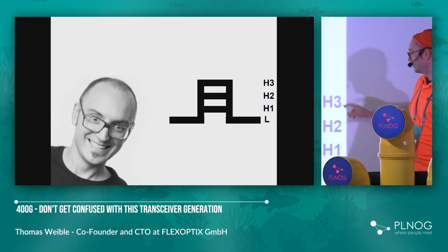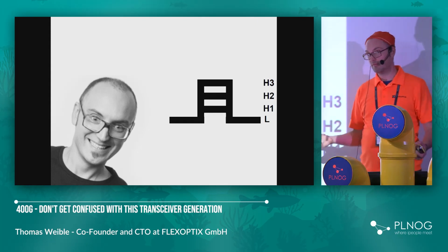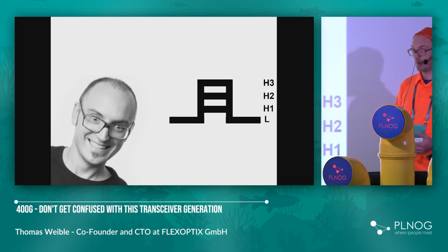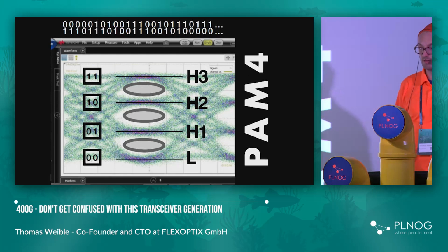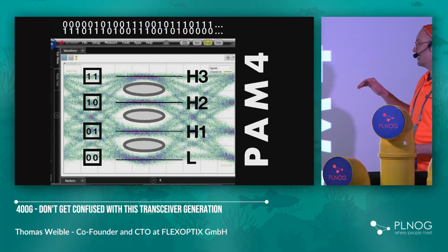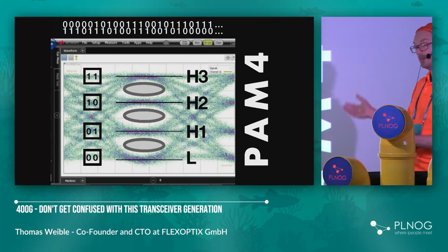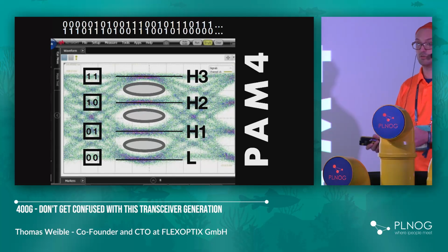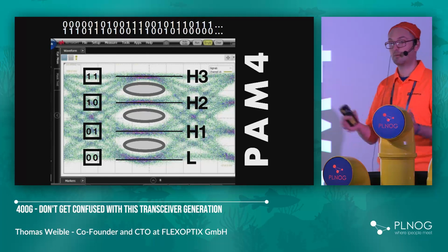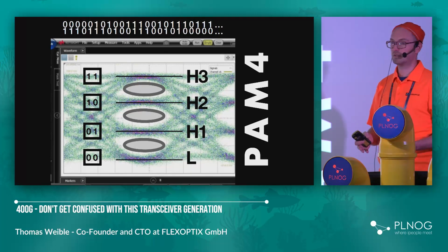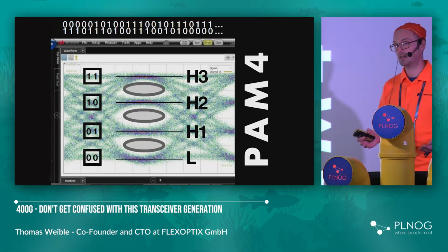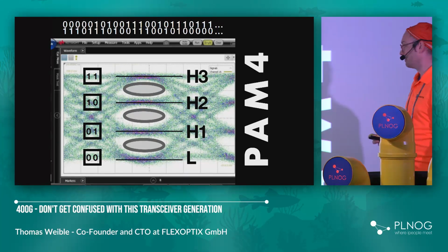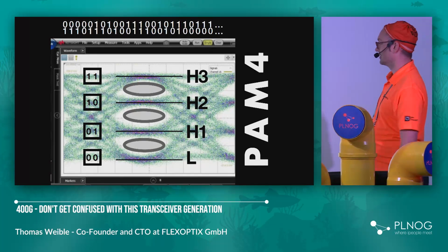So in total, these are 4 events. And the great thing about having 4 events in one pulse is you can represent 2 bits with it. So just with the amount within a single pulse on the same frequency like previously, we can encode or modulate basically double the amount of data bits in one single stream. And that's done with 4-level pulse amplitude modulation, which looks like this monster here, or that beast.